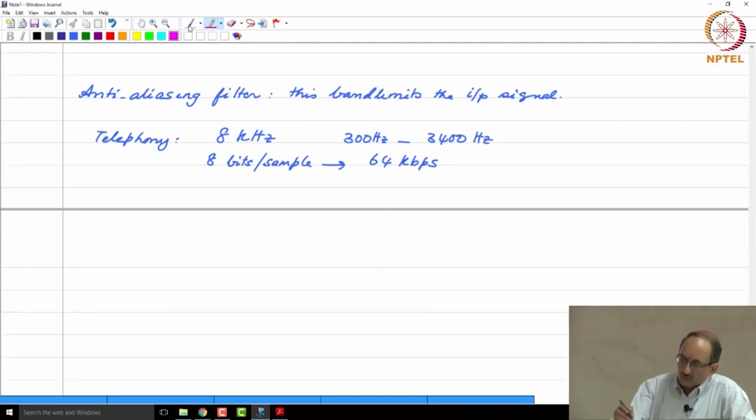Of course, now what we do is we do not use just plain sampling, we use speech coding. You sample it at a certain rate, we take 30 milliseconds of speech, sample it, and then use a source filter model and then transmit those parameters. So, the advantage is you get higher quality speech or you get a lower bit rate speech, but the price paid is more processing power. All this involves DSP processing. Anyway, coming back to sampling.